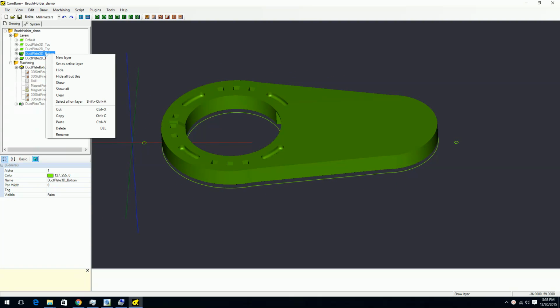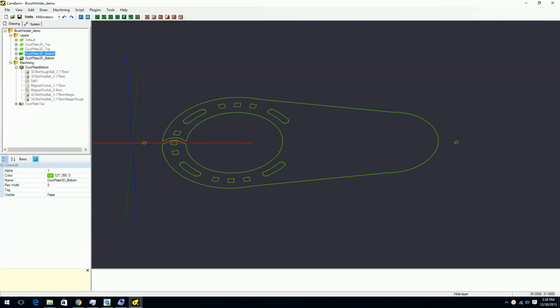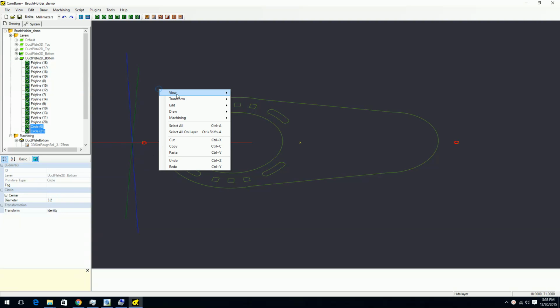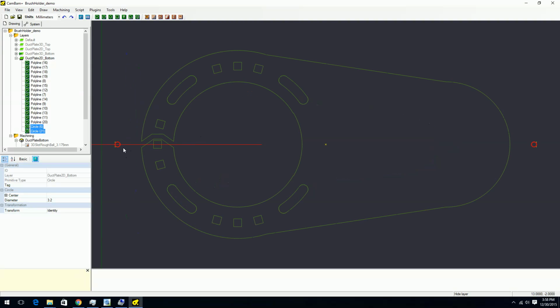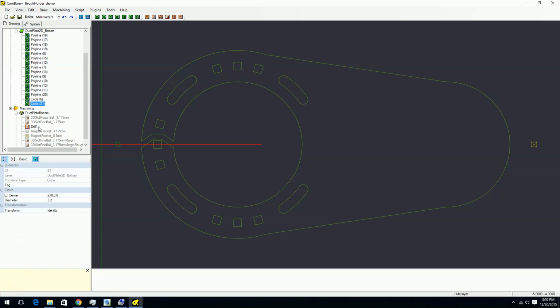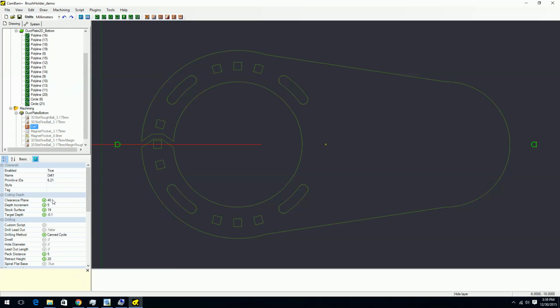So we'll start with machining the bottom part of the part. I created these two little circles here. These will be drill holes. I will use these drill holes to realign the part, the stock material. Since this part has to be machined on both sides of the stock, I will have to have a method so that I can rotate the stock around and realign the machine exactly so that I can machine both sides, and the machined sides will align to form a single part when everything is done.